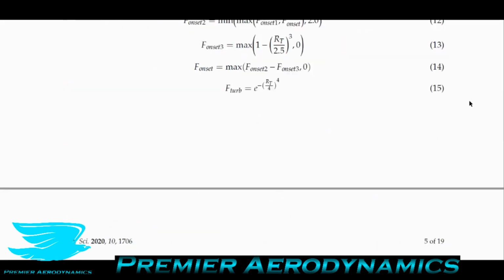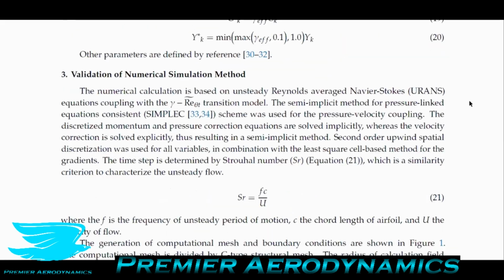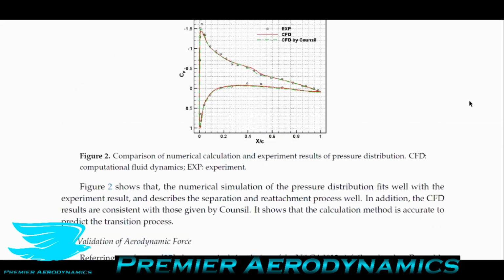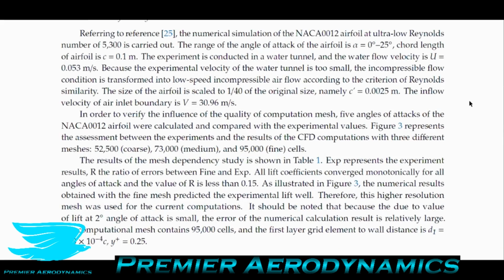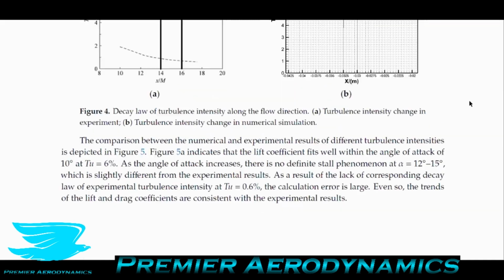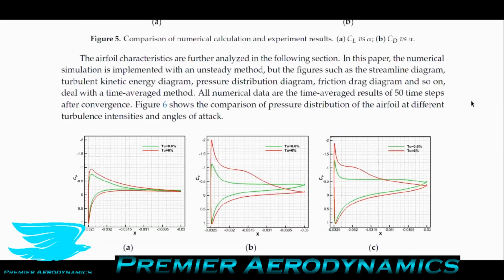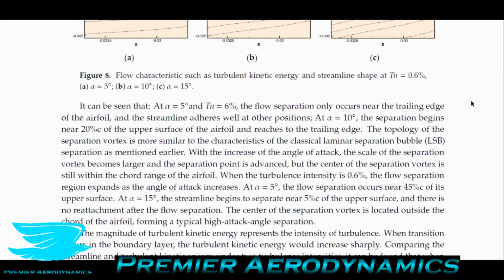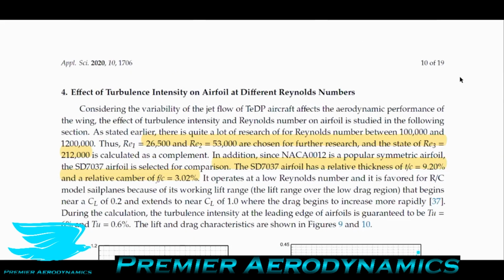And we usually measure it in the velocity in the free stream direction. You do have turbulence intensities in the other two directions, but they're not nearly as important as the free stream direction for a well-aligned flow, because in a wind tunnel you have your honeycomb, which aligns the flow very well. So you're going to be getting the turbulence intensity mainly in that direction, and that's quite important.